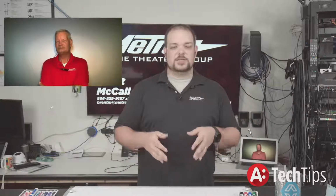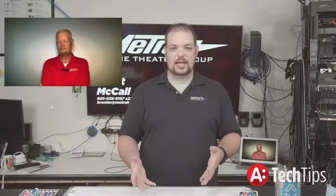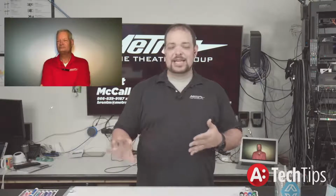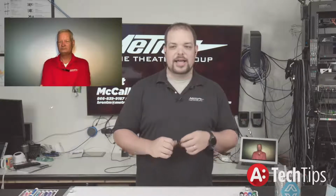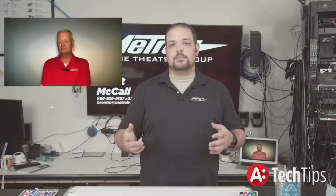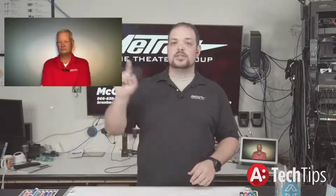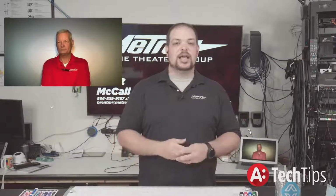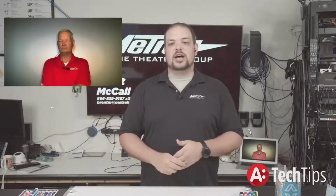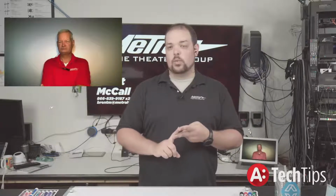As the matrix is being used with an AOC cable, the AOC is a fiber optic based cable where the data lines, or the TMDS lines, are fiber based. Because they are fiber-based, they require just a little bit more power. What we're seeing across the board is that many matrices out there are not supplying enough power, or the displays are not supplying enough power back to the matrix to power the output in order for the AOCs to work.